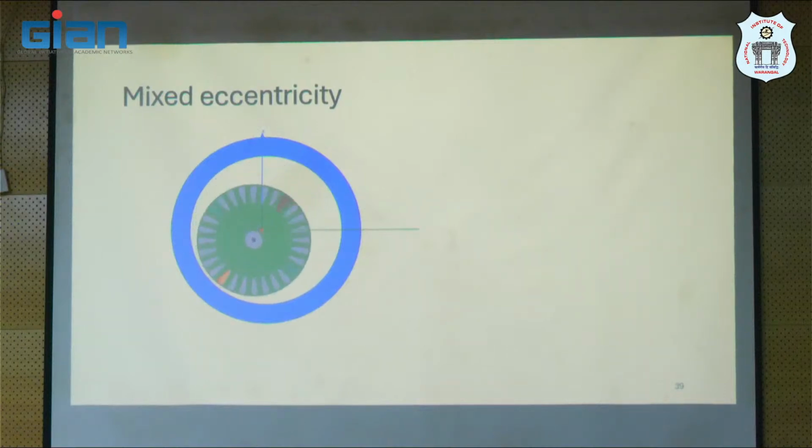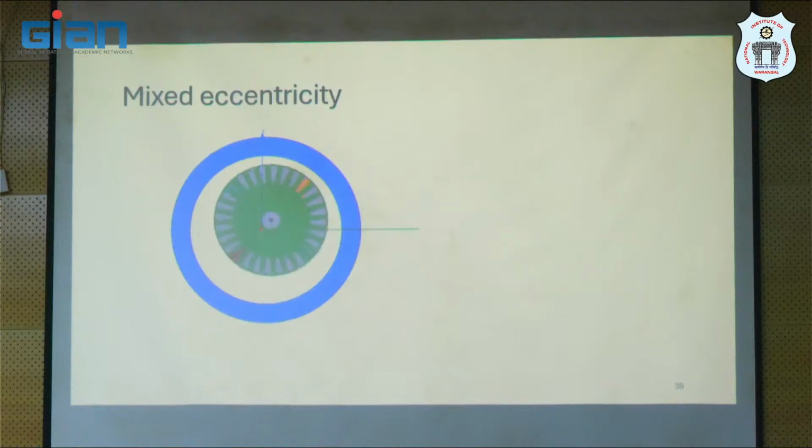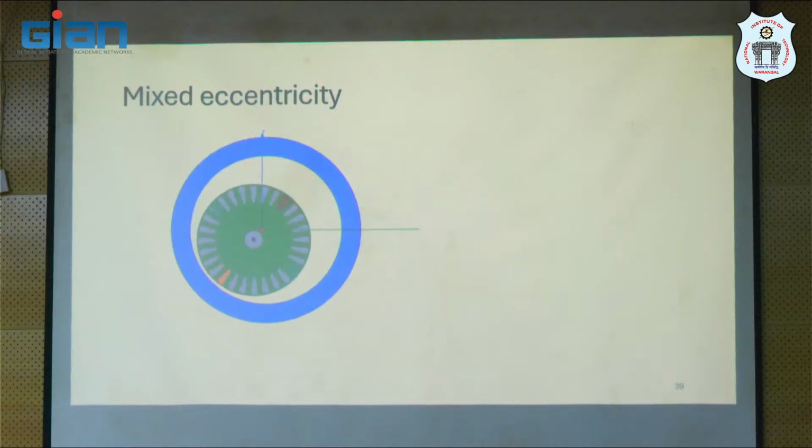So try to situate ourselves here on the inner periphery of the stator. I see that the gap changes with time. The minimum gap changes with time. So it's not a static fault, it's a changing fault. But if you plot the gap length seen by the orange bar with respect to time or with respect to angle as you go around, you may not get a constant line. Right? Do you agree? Locate yourself on the orange bar along the x-axis to begin with, and as you go through, what happens? Things change, right? The gap length changes. It either decreases or increases, it doesn't really matter.